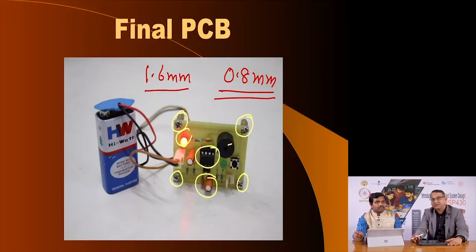If your circuit is complex enough to merit a multi-layer board, beyond single sided you have double sided, you also have 4 layered, 6 layered, 8 layered, or even 20 layered PCBs. For that it will be difficult to prototype in the lab, and the best way is to send out your layout to a PCB fabrication facility which has the capability to fabricate PCBs with the number of layers that you wish. Once you do that, you get the PCB back, then you can solder manually, as I mentioned.